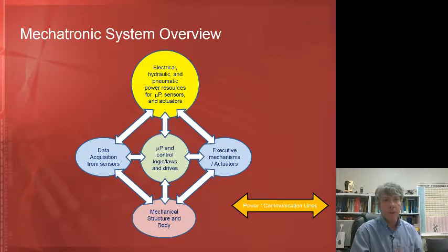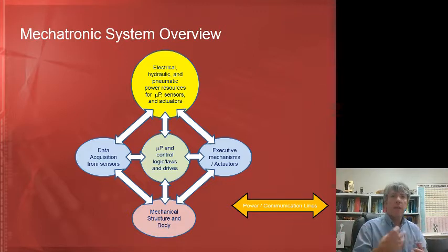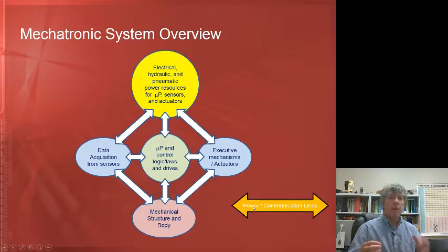Even the Arduino we're going to use, yeah, it can drive really small motors, but if you have any decent sized motor, you need something to drive that motor. You need something that is sensitive to the signals that come from the microprocessor, or the microcontroller in our case, and then amplifies those signals and then can drive power to a larger motor. So this power line, that's something where we have to have some external power that the microprocessor can basically redirect.